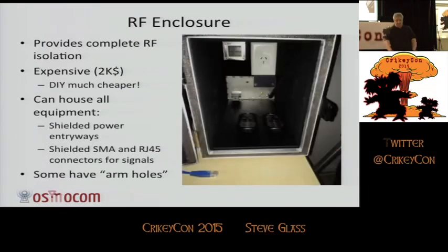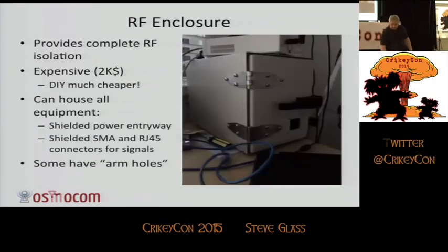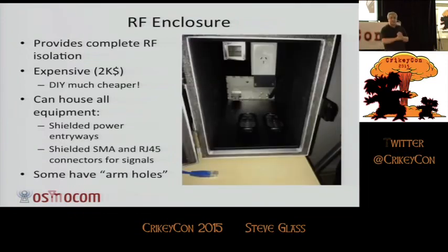Mine, look at it. On top, if you look back at the last photo, my USRP. The antenna you can see is just the GPS antenna that I use for the clock. The cables coming out the front go into the back of the case and come up with this little antenna inside. So my kind of RF world is a little space like this. But it's enough for me to be able to talk to any mobile phones I've got, put them in there, I can send SMSs to them, get them to register.